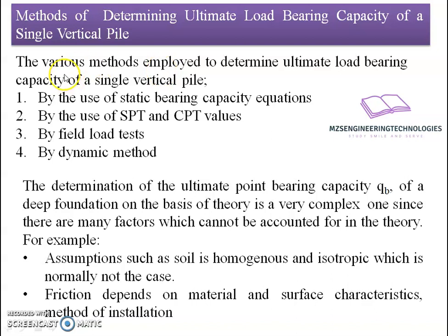Greetings. Let us continue with the part of estimation of ultimate load bearing capacity of single vertical pile. Various methods are employed to do so. They are first, by the use of static bearing capacity coefficient, by the use of SPT and CPT values, by the use of field load test, and by dynamic methods. In dynamic methods, some empirical formulas have been suggested for the determination of bearing capacity.